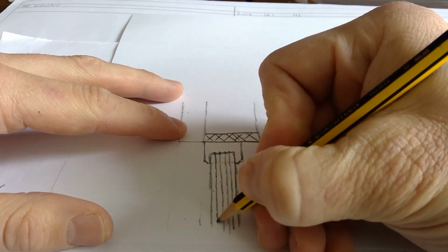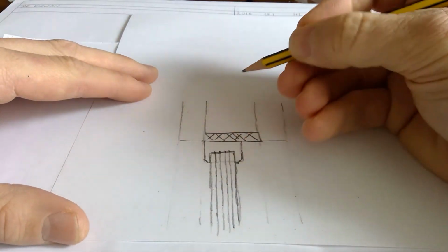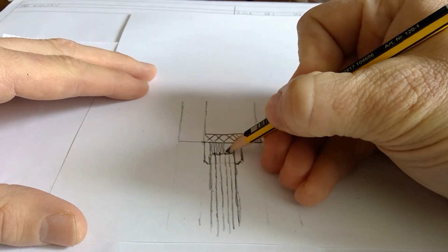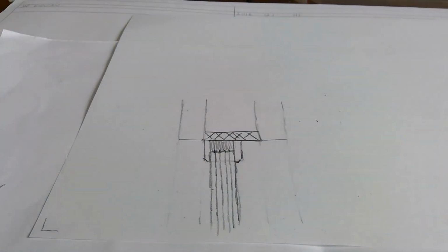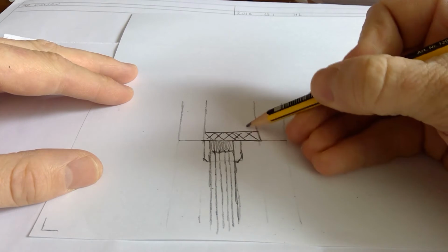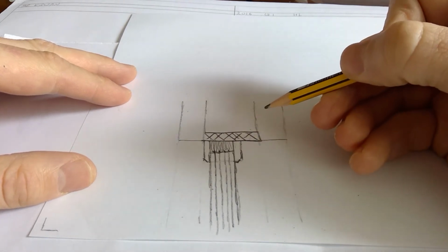And there's your triple glazing of the window. It's a thermally broken window frame, so make sure you add some insulation in there in the middle of the frame. Alright, again you can see the cavity closed there because if not there'll be a big gap in that.